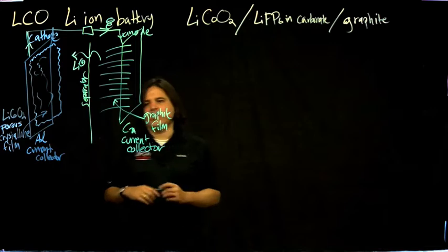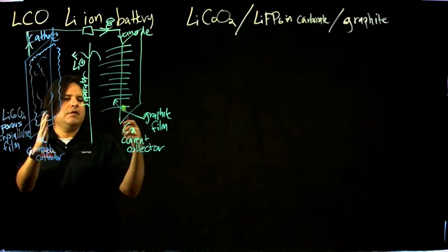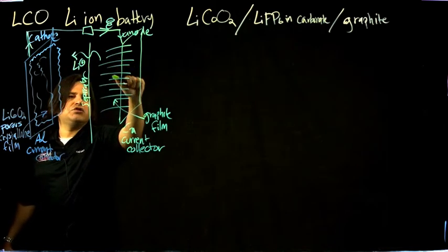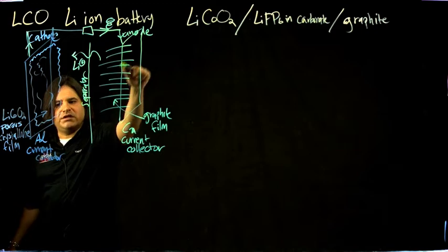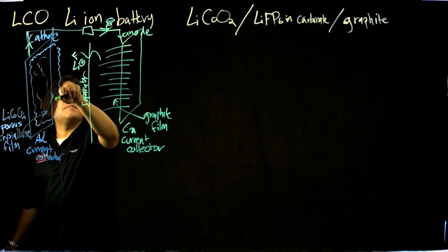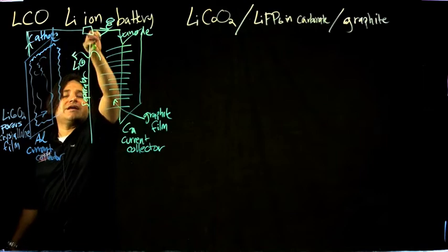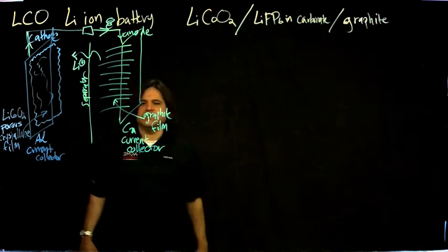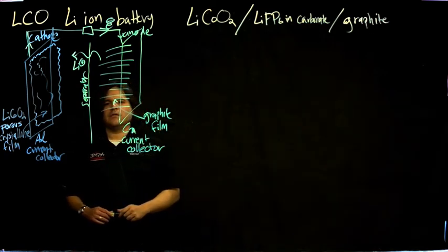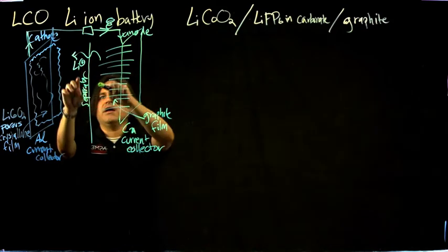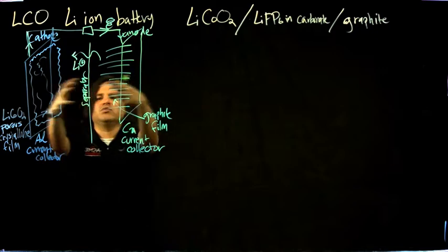So that's what we're doing. We're creating a voltage across here. And then that voltage is due to this lithium charge. When it's charged up, it sits on the graphite. When it discharges, it goes back into this lithium crystal lattice. And because of the separator only allowing the cations back and forth, the circuit goes in either direction. Because the charge does not equalize here, it equalizes by a circuit instead of just within this electrolyte.